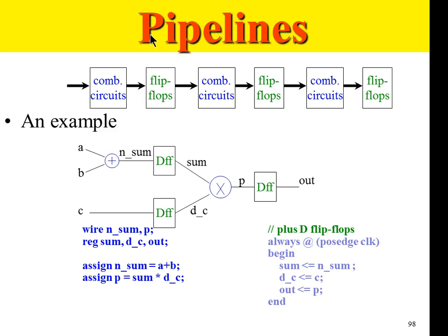Sometimes what happens is, with this combinational circuit, let's say I remove this flop. So let's say combinational circuit sections 1, 2 and 3 followed by a flip flop. This is going to be a very long path by the time it gets registered. The part from input to the flip flop output is considered one path through the combinational circuit in static timing analysis. If you remove the flops in between, it's going to be a very long path. Chances are your design is not going to meet timing.